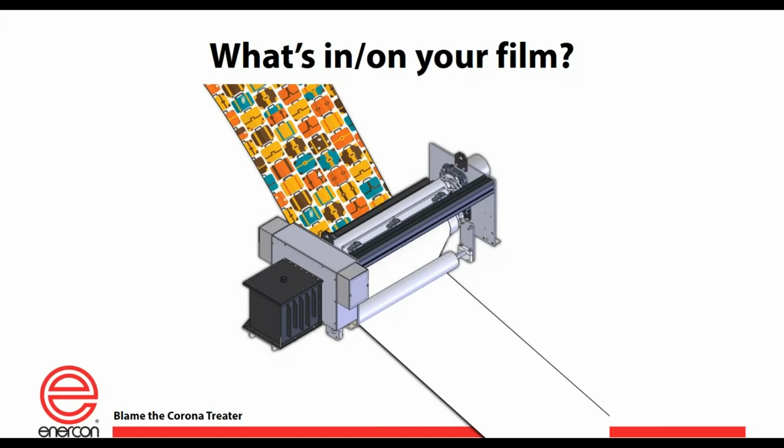So let's take two extreme examples here. We'll have a virgin polyethylene film in one example, and then we'll have a polyethylene film that has a high slip content and a bunch of antiblock. Now, if you're not aware of these details, and all you were paying attention to is that the film is polyethylene, and you put the job up on the press and you're running these two jobs, and you weren't paying attention to the differences between those two films, it's very understandable why in one case you'd be successful at a given corona treater setting, while in the next case with the same setting, you would not be successful at all.